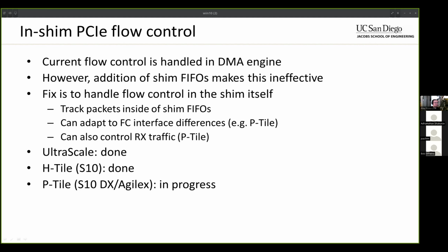But yeah, I think that's a combination of this write count limit, limiting it to like 3 operations, in combination with the higher latency of the FIFOs and the MUX in the shim. So yeah, with that count lifted to a higher value, then it should, I think, perform better.